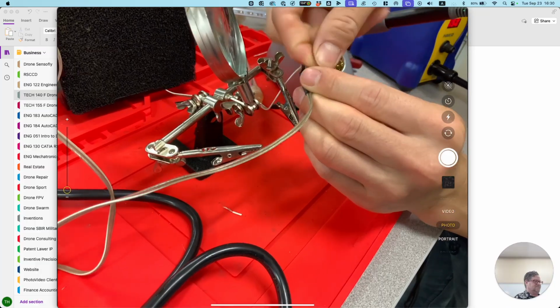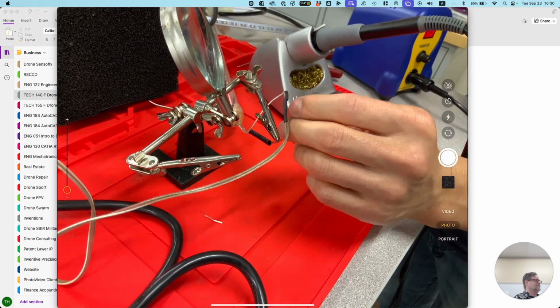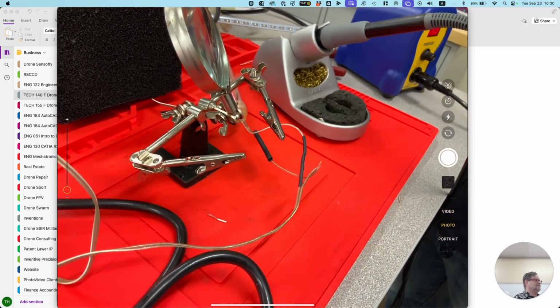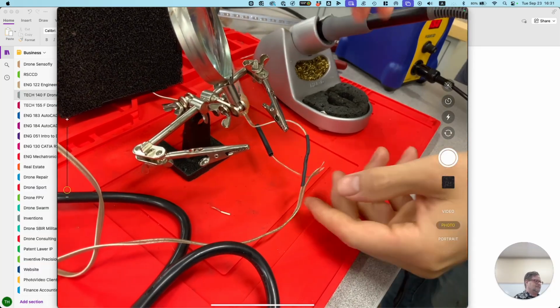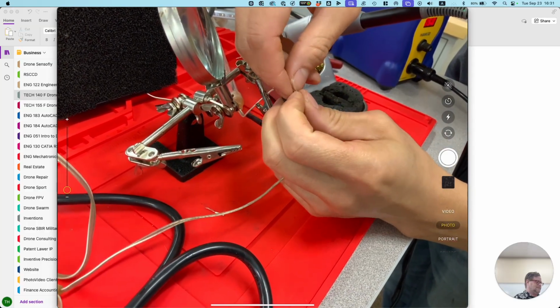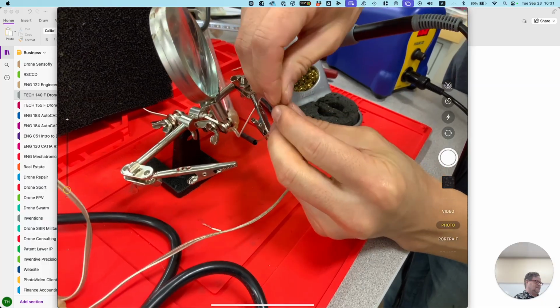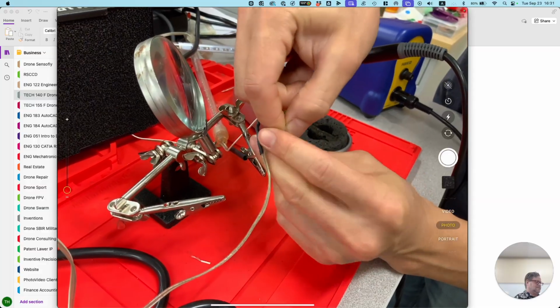What you would do is take an X-Acto knife, cut a little corner, and then peel the rest open. If you try to cut down the entire line, there's a good chance you'll cut the wire as well. After this demo, we can practice on your own wires.